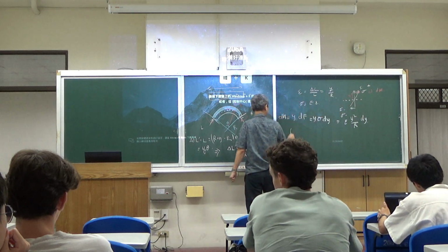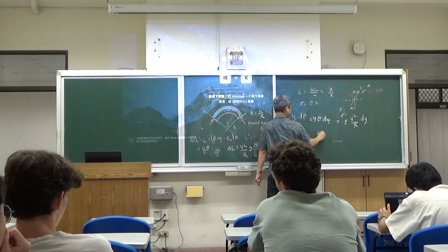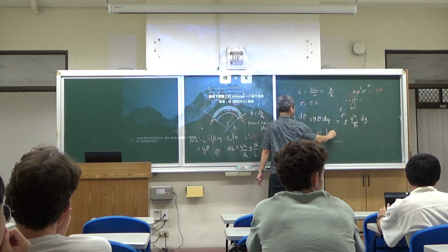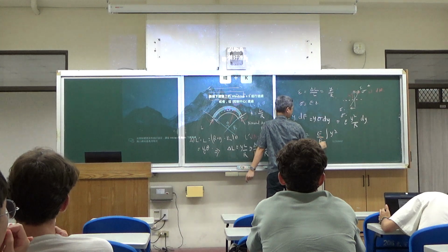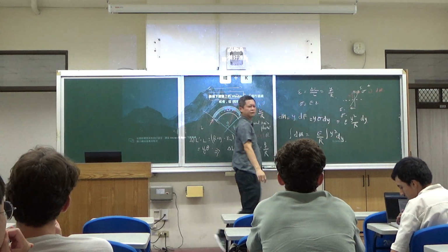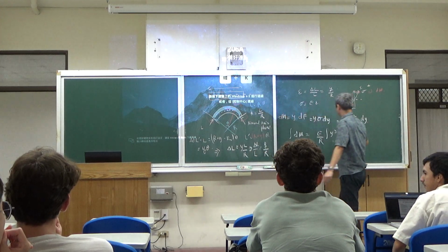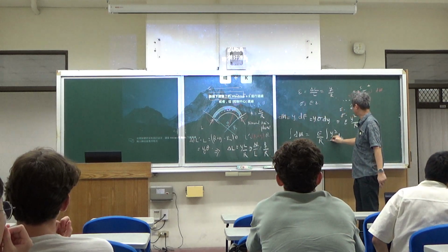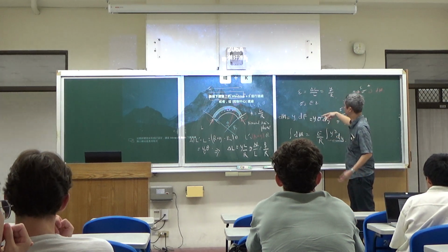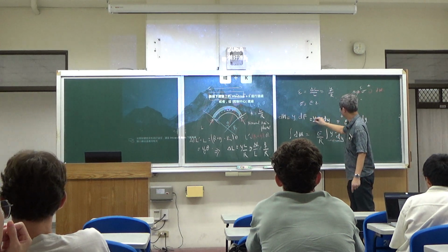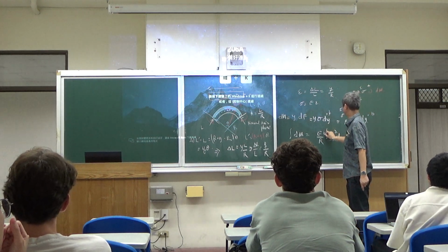If you now integrate the small moment, you're going to have E and then y squared. Because of the common radius here, take the radius out, and then dy. So the total moment required to do this bending is this expression. I forgot to include the area. The area will be the width, let's say b, times dy.